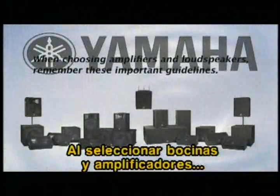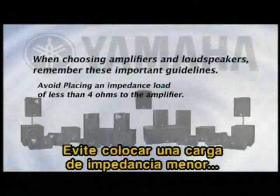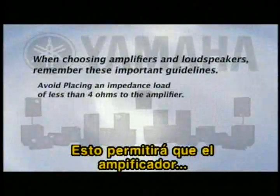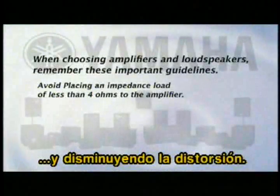When choosing amplifiers and loudspeakers, remember these important guidelines. Avoid placing an impedance load of less than 4 ohms to the amplifier. This will allow the amplifier to run more efficiently, reducing heat and decreasing distortion.